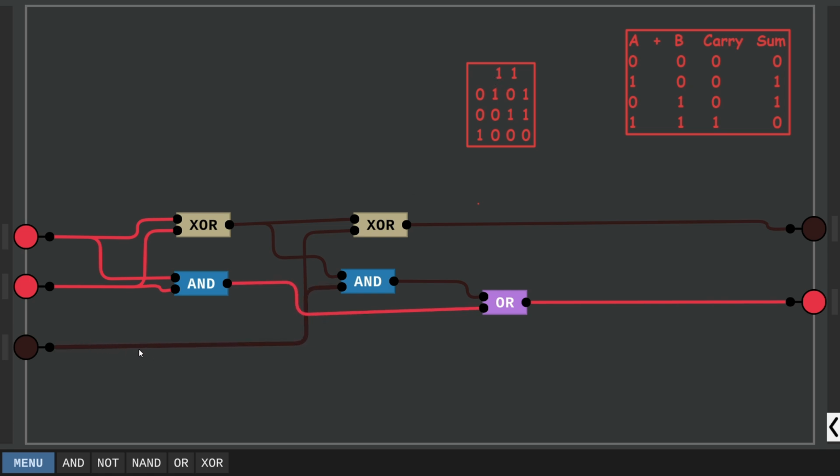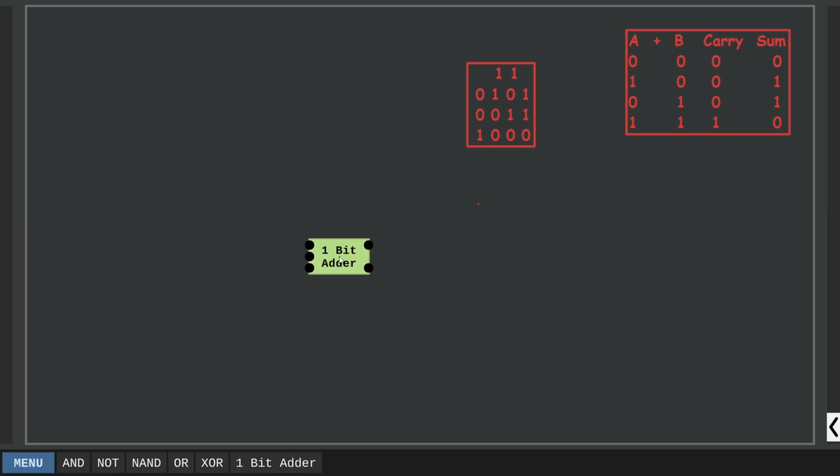So we can use an AND gate to check that, and we can use an OR gate to check if there is a carry from these 2 bits or this carry, then we will output that carry to the next bit, as you can see here from this pin.